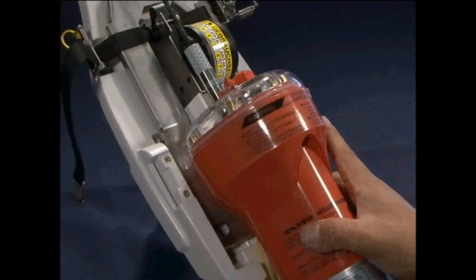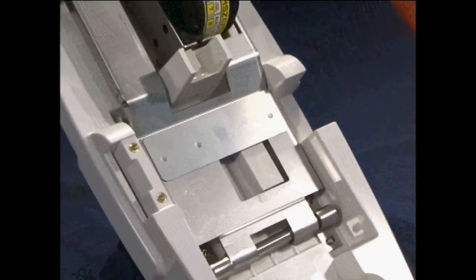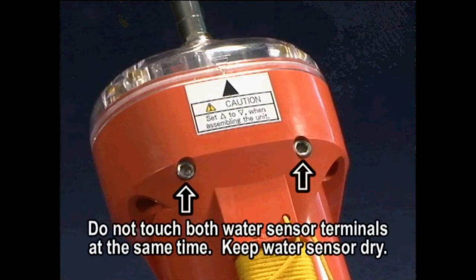Since water pressure is required to trigger the equipment, accidental signals will not be transmitted if the EPIRB is detached from the automatic releasing unit in a dry environment. However, transmission will start if the water sensor terminals are splashed with seawater or touched by a wet hand.